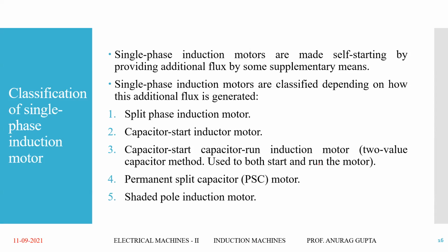Next we discussed why induction machines are not self-starting, and what is the meaning of the double field revolving theory. On the basis of that theory and the discussion of why single-phase induction motors do not self-start, we discussed classification. If single-phase induction motors are not self-starting, we have to provide some additional flux or supplementary means to start.